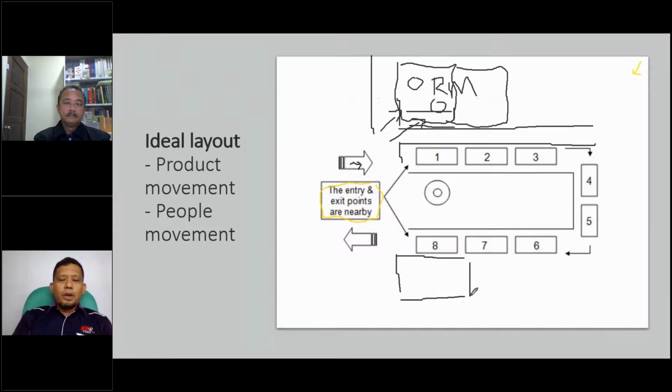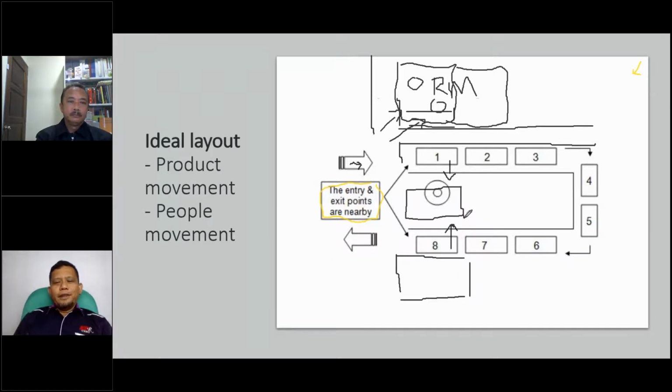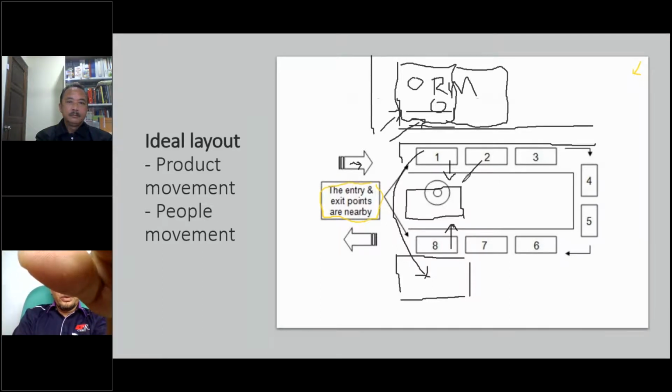All right. So if the product actually comes from process number 1 and number 2, then I propose the finished good warehouse should be in the middle. Because if the product from number 1 goes to here, I consider it quite far also. So if the product comes from 1 or from 2 to the warehouse straight away, then we can put it in the middle. If the process is really like a U-shaped process, then the warehouse can be put here. Okay, I prefer the middle.